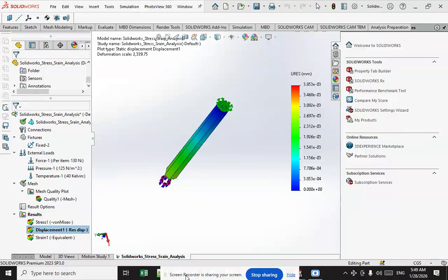The first one is tensile testing. It is a fundamental material science test in which a sample is subjected to a uniaxial tension until failure. The results from the test are commonly used to select a material for an application, for quality control, or to predict how a material will react under other types of forces. Properties that are directly measured via a tensile test are the ultimate tensile strength, maximum elongation, and reduction in cross-section area.